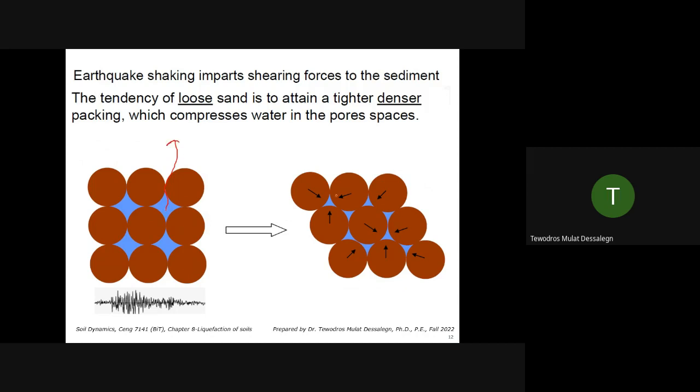But in this case, it's confined. So high water pressure occurs. Shaking the loosest configuration with water results in trying to turn into a compacted state, but high water pressure comes in between.